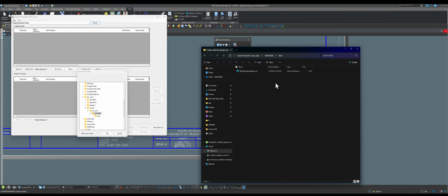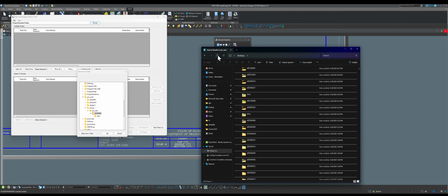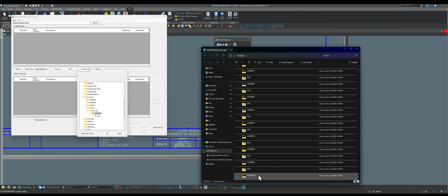Inside it, this DMS folder, which is again part of the blank template, opens an empty blank DGN that has the FDOT logo attached inside it. So I don't care about this. There are two ways of doing this. You find this folder, you right click on it, you delete it. Or you type old, and if you are afraid to delete it, because I've seen some people are scared, but if you delete it, it doesn't matter. So I'm going to try both ways.